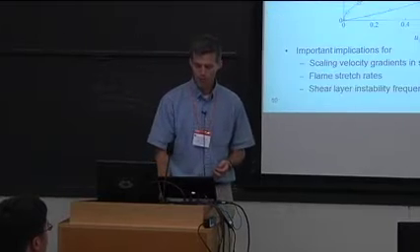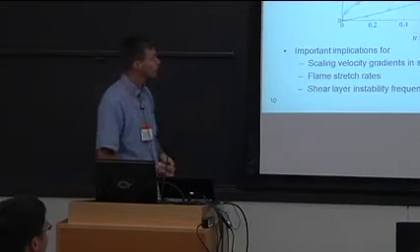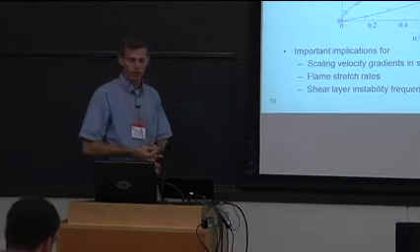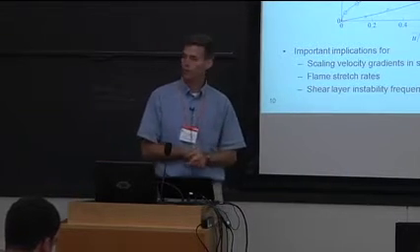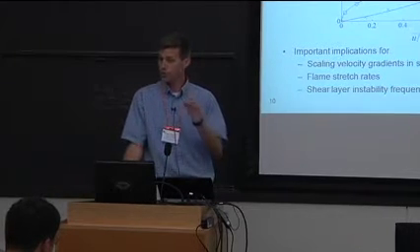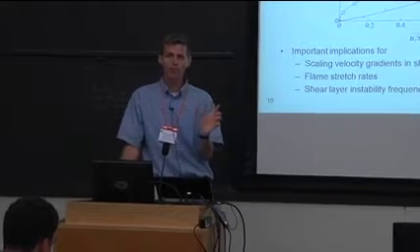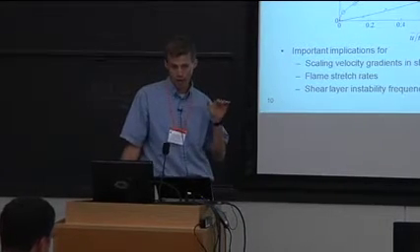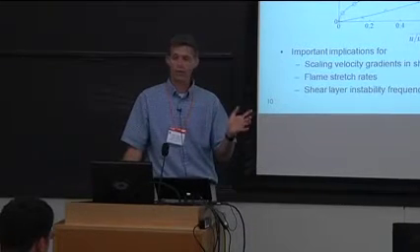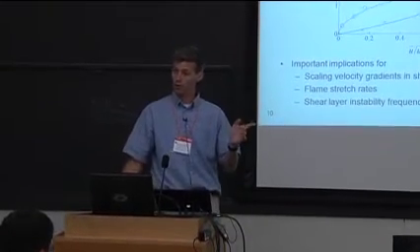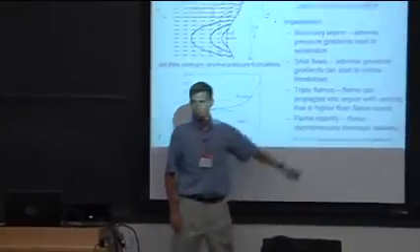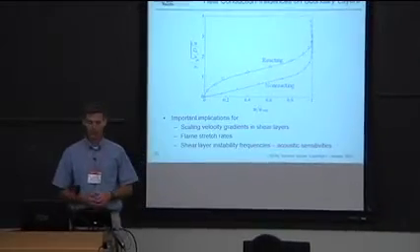And so think about what happens if you have combustion. Well, combustion causes back heat transfer along metal. It causes heat transfer to boundary layers. All right? So if you look in Schlichting's boundary layer book, there are some problems on boundary layers with heat addition. I'm not going to prove it to you, but you take your boundary layer equations and you can prove that if you have heat addition in a boundary layer, it causes an inflection point in your boundary layer, just like an adverse pressure gradient does. So not only does a flame with curvature give you an adverse pressure gradient, but also the fact that you have boundary layer heating causes an adverse pressure gradient.